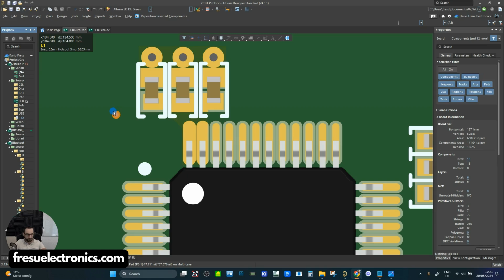But what we want to do is to select a certain value of capacitance for the chosen package, so that then we can calculate how many of these capacitors we are going to need in order to build the impedance profile that we want. This will become very important because each time that we are placing a capacitor, we have to think not only that we are placing a capacitor, but that we are placing an LC network. And this is important because this means that we are going to have also some resonant frequencies, as we know from LC circuits. And then we have to be careful about this type of phenomenon.